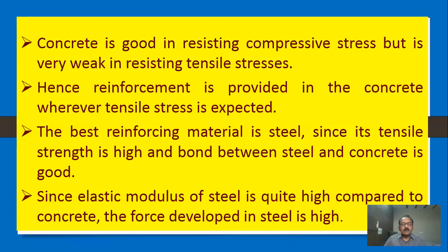So that's why we provide tensile reinforcement. And one more important point is why we use steel in RCC: because there is a good bond between steel and concrete. Wherever tensile stresses develop, we provide reinforcement.